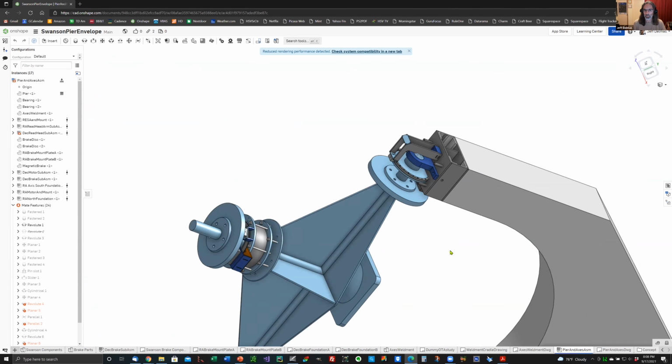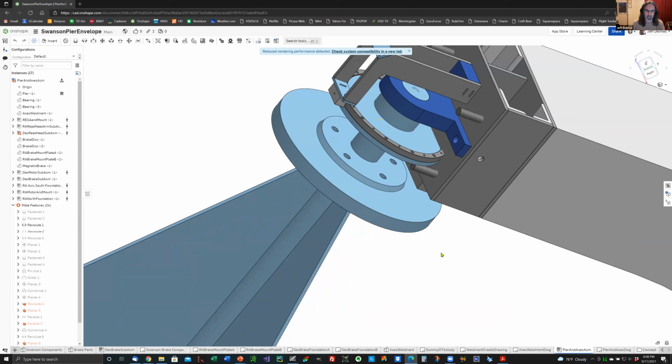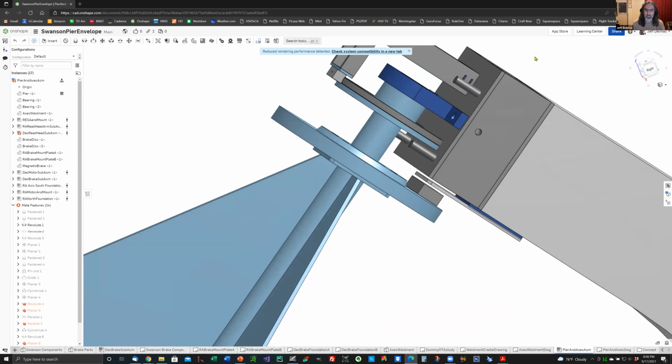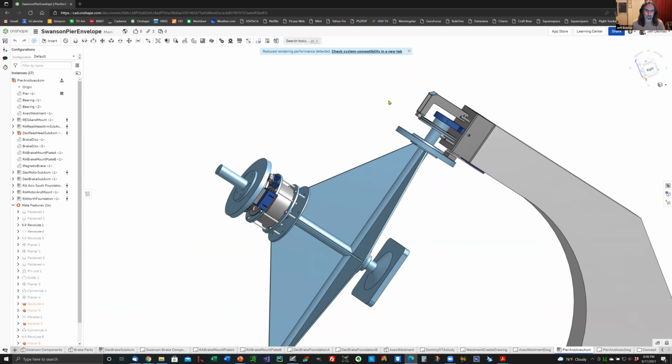So the brakes will actually be on all the time. And once we turn the system on to activate the telescope, then the brakes will go off and the motors will engage. And it turns out that even if the brakes fail, if power goes out to the brakes, there's residual torque, enough friction on here that things aren't going to go flying around, in other words. But having those brakes will stop any motion that the telescope may have due to imbalance. And that's really the only kind of torque. If the telescope is perfectly balanced, there is zero torque at rest. But that's never the case. And the larger the scope, the more of a problem that becomes.